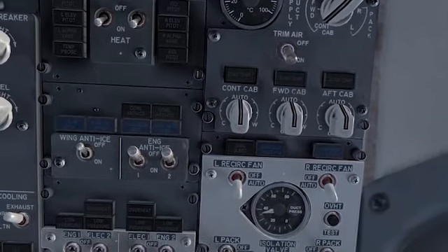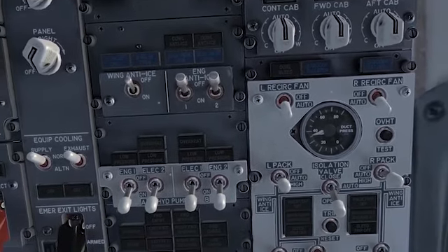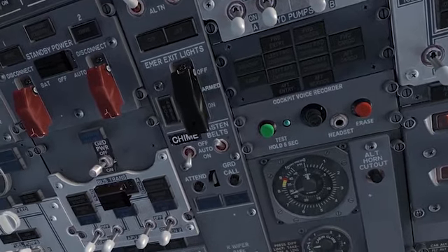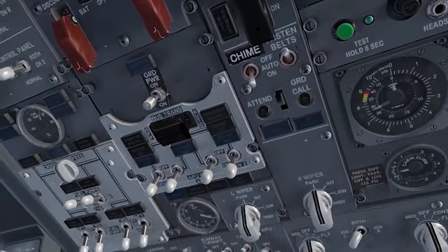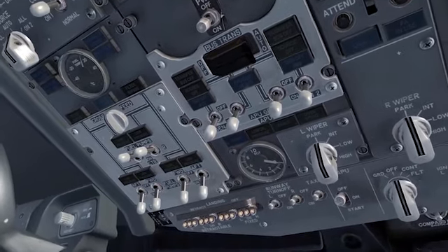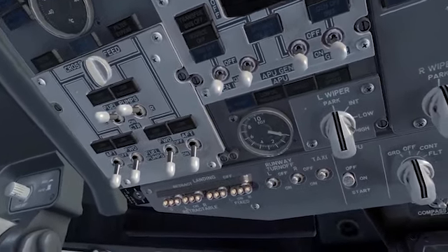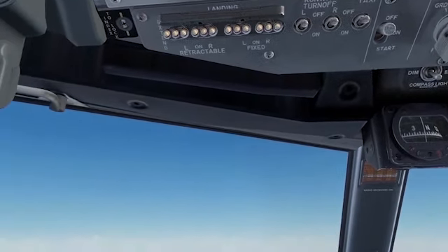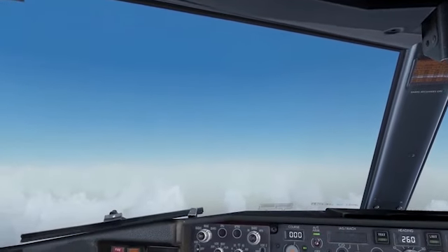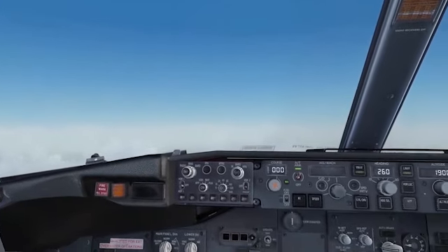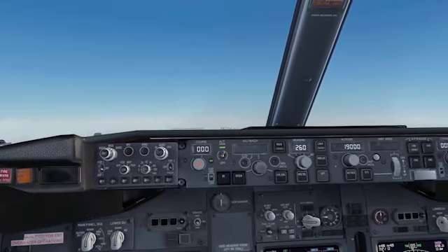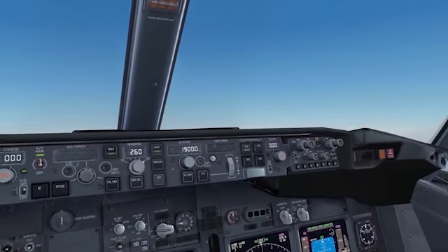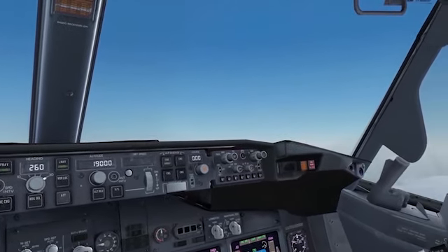Naturally, if one pack fails, the other pack automatically switches to high airflow to supply the demand for conditioned air and ventilation. This protection mechanism is only available during flight when the trailing edge flaps are in the up position. Similarly, like in the case of a bleeds-off takeoff, where both engine bleed switches are off and the APU is supplying pneumatic power, the packs deliver high airflow regardless of any flight parameter. For a detailed explanation of the bleeds-off takeoff procedure, watch the 737 NGX line work bleeds-off lesson.